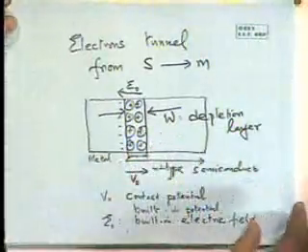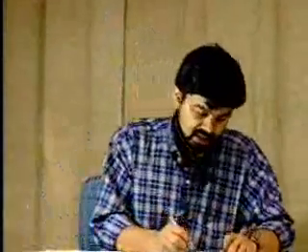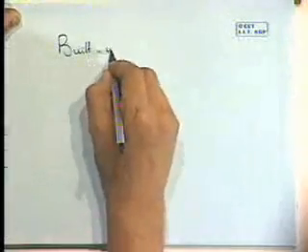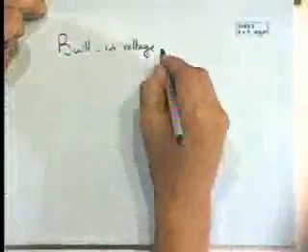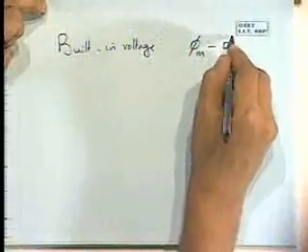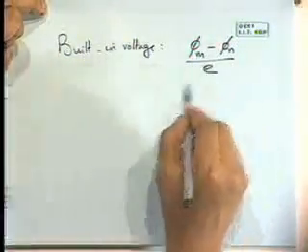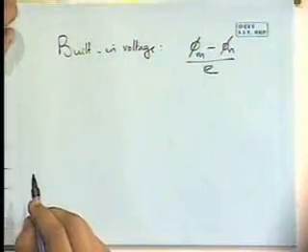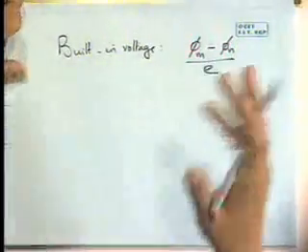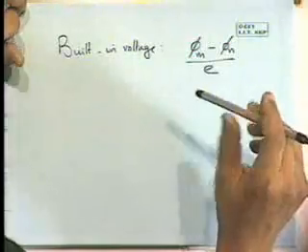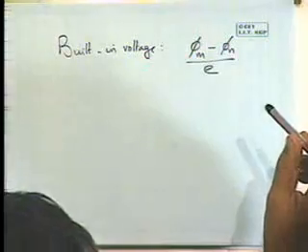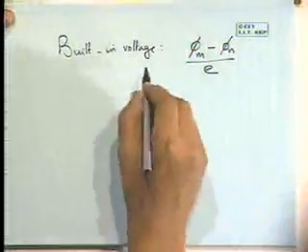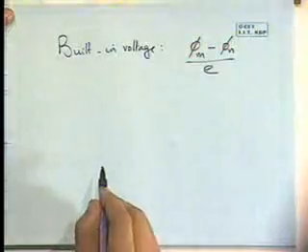So this is the situation in equilibrium, and when we look at that, the built-in voltage, if we analyze it, that is going to be established, will be given by phi m minus phi n. We can see that shortly also. If you consider two metals, we will see this to be the case much more easily, but the same idea is here also. That difference in work function between these two is what will be the built-in potential, or built-in voltage. And potential accordingly is simply phi m minus phi n.